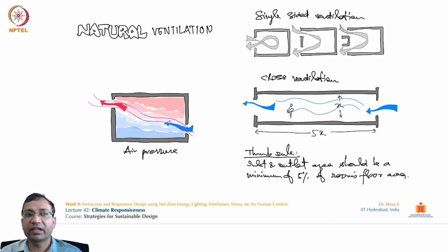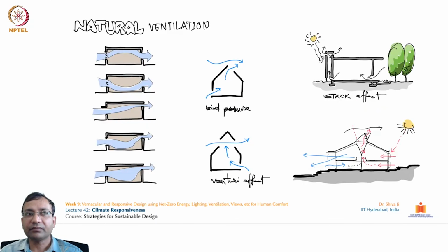The strategic location of the inlet and outlet points also should be decided, because if we want a scouring effect of wind inside the space, to have the maximum effect, the location of these entry and exit points could be at the diagonal level. That will maximize the overall efficiency for the cooling effect.